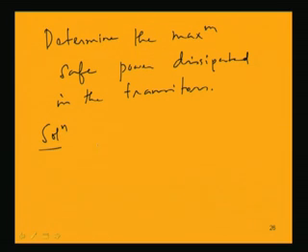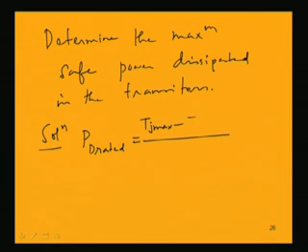We know the power dissipation which is rated, PT rated, that is given by Tj max minus T ambient. T ambient is 25 degrees centigrade, even if it is not mentioned you should know it, divided by theta device to case.